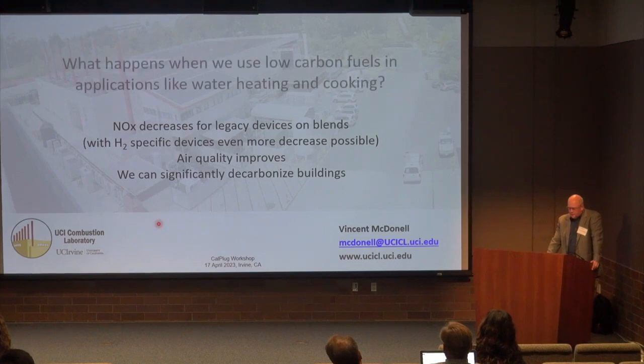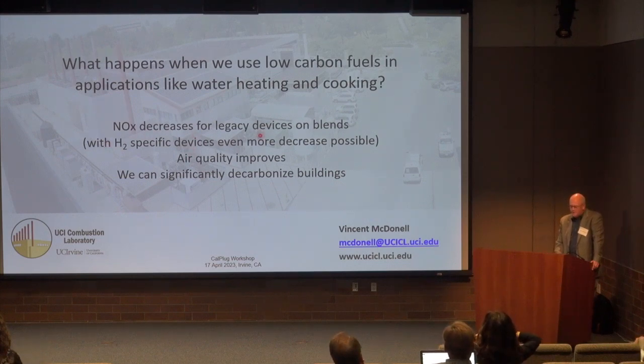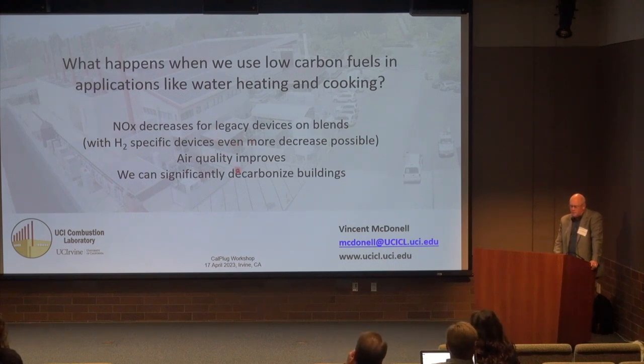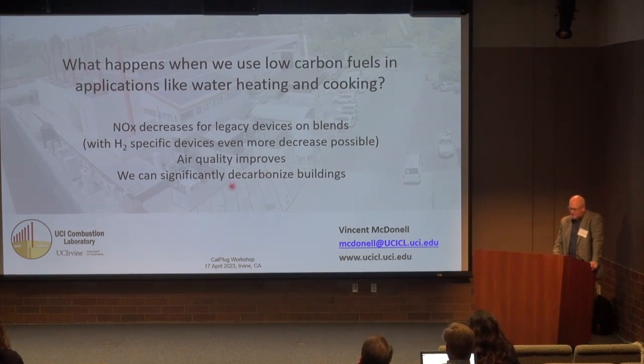If we go back to the question, what happens when we use low carbon fuels? Well, we see that for the most part, NOx actually decreases for legacy devices. And if we know that we're going to be blending hydrogen or that we're going to have 100% hydrogen, we know what to do to design these devices to achieve even lower NOx emissions. And this translates into an air quality improvement and the ability to significantly decarbonize buildings.